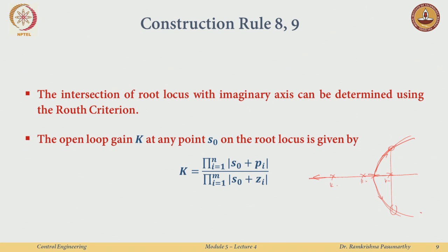Now, can I really compute the value when it becomes unstable? There was another example where my poles were here, here and here, and then the root locus had one branch moving this side and the other 2 going here. So for any value of k greater than 0, it was always unstable. That was not difficult to compute. Now, how do I handle these conditions?